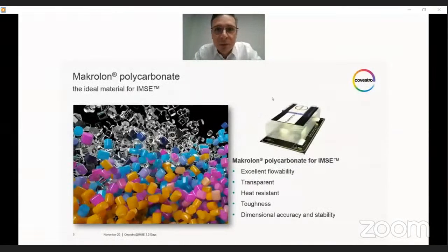Yeah, thanks, Florian. My name is Fabian Grote from our polycarbonates business. And let me explain first why polycarbonate is really the only available option for engineering plastics to fully exploit the potential of in-mold electronics. Polycarbonate is an amorphous polymer, which is available in low viscosities to ensure good processability. Polycarbonate is transparent, enabling light integration into IMSE devices, and we will see lots of examples today and also tomorrow in the sessions.